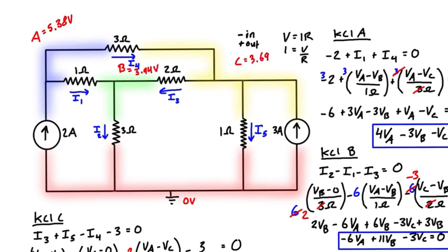And then we can see I3 here has to be switched in the direction, because right now we've labeled it as flowing from a lower voltage to a higher voltage, and that doesn't happen across resistors. So we just need to change the orientation here. I'll just draw over it maybe with a black arrow. It's actually going to the right, and then basically if you were asked to solve for the voltage drops and the currents in these resistors, that's a really quick operation that we can do as well.